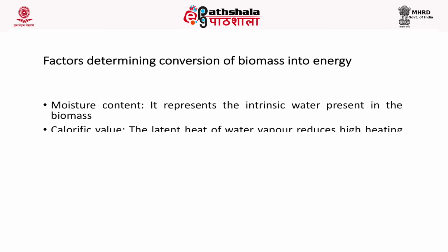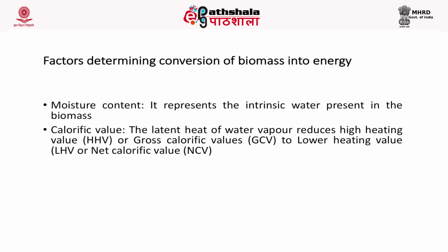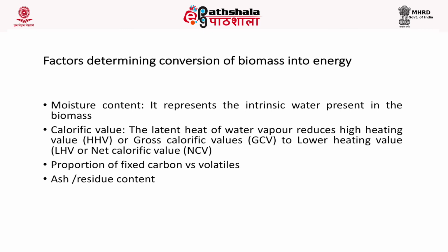Moisture content represents the intrinsic water which is present in the biomass. Calorific value: the latent heat of water vapor reduces the high calorific value, or the gross calorific value, to the lower heating value, or the net calorific value. Proportion of fixed carbon and volatiles, ash residue content, silica content, cellulose-lignin ratio. All these affect the biomass conversion into energy.